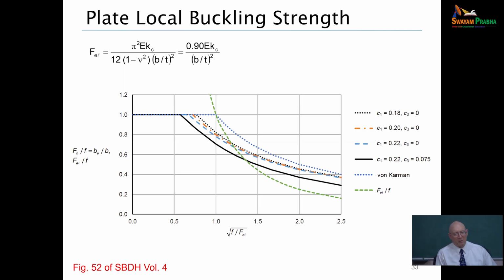And so when we were looking at all that with bringing forward provisions for designing massive longitudinally stiffened boxes and, say, bridge towers in the bridge standard in the US, we decided, okay, we don't want to be pulled out of our grave because some signature bridge failed because we screwed up in the standard. And so we went with the more conservative UK results for the plate local buckling strength, the black curve here. And we did that by just doing a very simplistic reduction from Winter's curve.